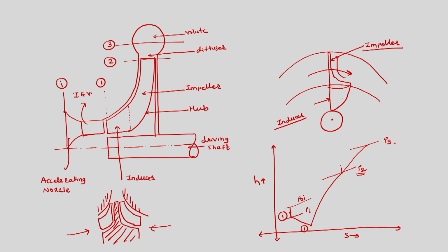But if we would have isentropically compressed, we would have got to P02. If we would have compressed isentropically for the diffuser exit, then we would reach the same total temperature, but we would have lower total pressure as P03.